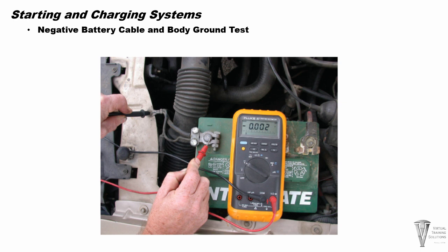Many repair jobs require disconnecting the negative battery cable from the engine. Always double check that the negative cable is bolted tightly to the engine before you restart the engine. The engine usually cranks and starts even though the negative cable is loose at the engine. Current takes the path of least resistance back to its source, the battery. Now the path of least resistance from the starter back to the negative battery terminal is through the transmission links or cables, the body, and then through the body ground.